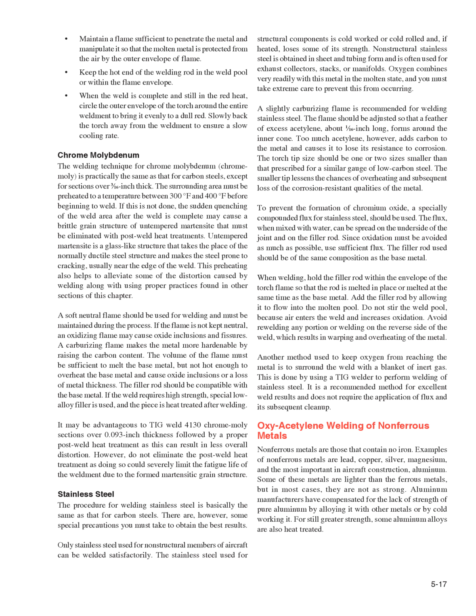Oxyacetylene welding of non-ferrous metals. Non-ferrous metals are those that contain no iron. Examples of non-ferrous metals are lead, copper, silver, magnesium, and the most important in aircraft construction, aluminum. Some of these metals are lighter than the ferrous metals, but in most cases, they are not as strong. Aluminum manufacturers have compensated for the lack of strength of pure aluminum by alloying it with other metals or by cold working it. For still greater strength, some aluminum alloys are also heat treated.